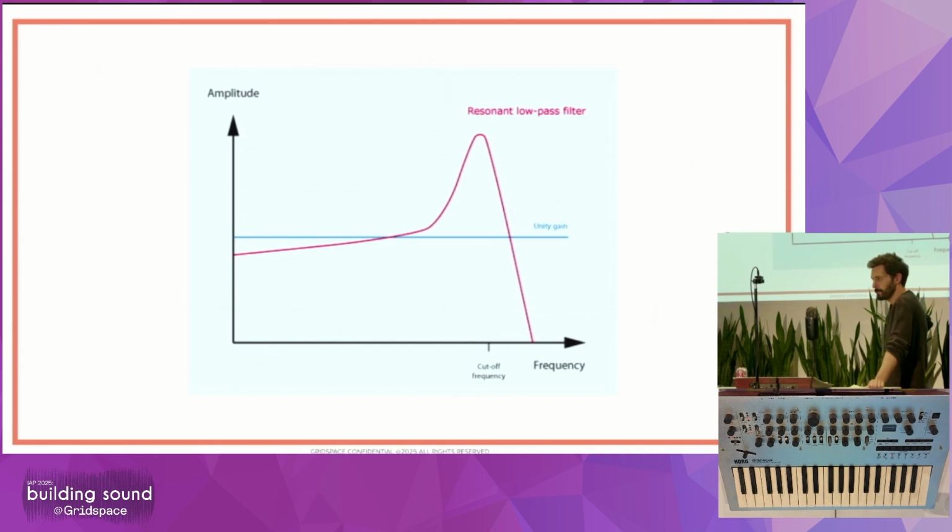Yeah, I mean, you've seen what aliasing looks like, the artifacts from a digital low pass filter. It creates these lobes. So similarly, even in digital, you can't have a perfect low pass filter, but that is more from the limitations of sampling than it is because of the limitations of analog electronics.